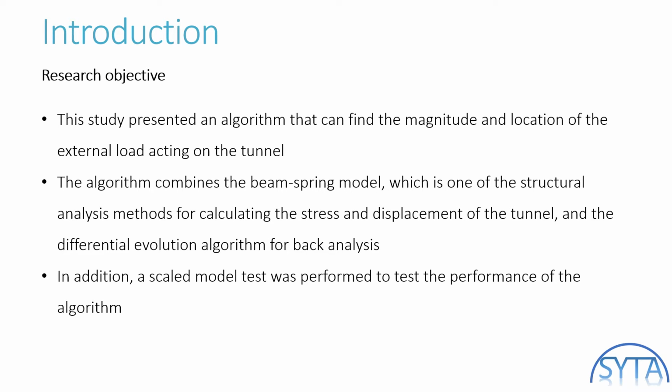So my research presents a back analysis algorithm that can find the magnitude and location of the external load acting on the tunnel. The algorithm combines the beam spring model, which is one of the structural analysis methods for calculating the stress and displacement of the tunnel, and the differential evolution algorithm for back analysis. In addition, a scaled model test was performed to test the performance of the algorithm.